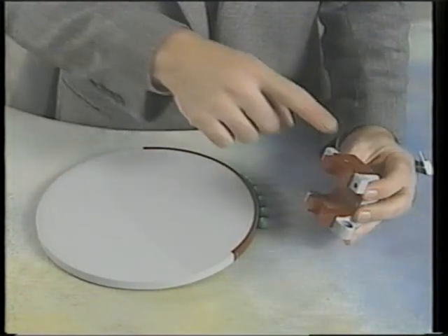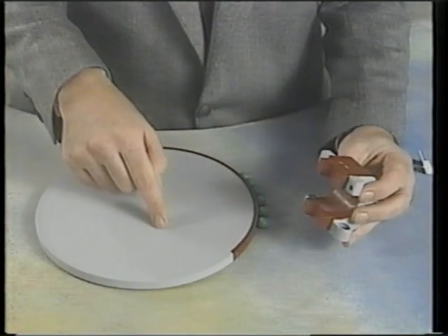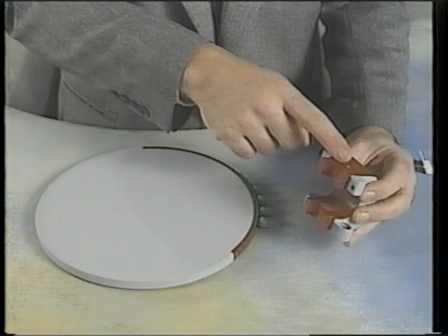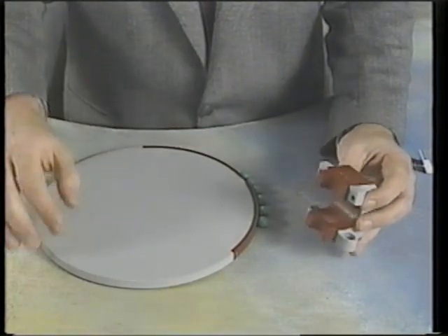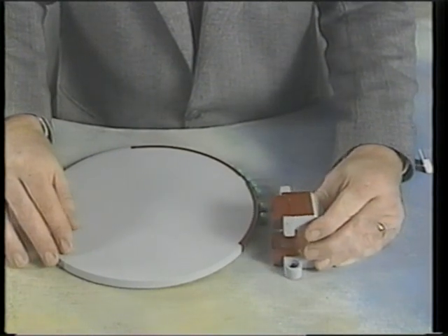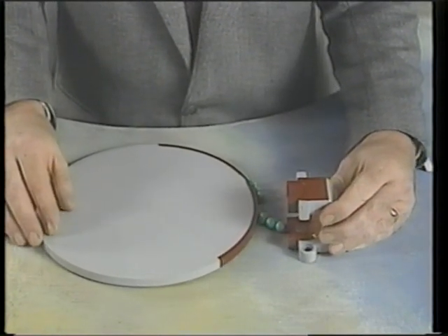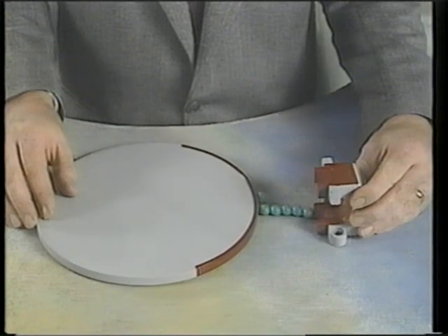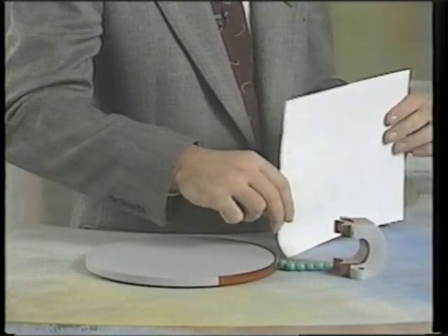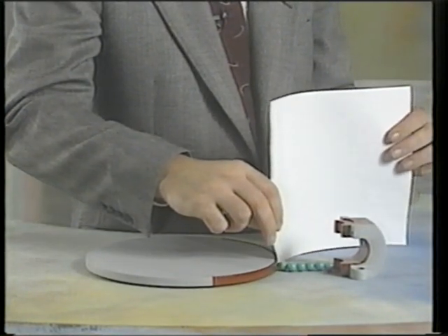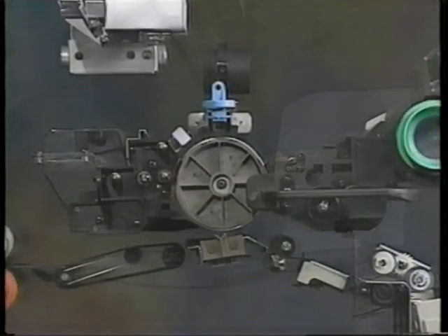It's another case of a strong attraction encountering a weaker one. In a copier, the transfer corona creates an electrical charge stronger than the latent image. The result, when the drum turns past the transfer corona, the toner is attracted away from the photoconductor. There's one other element, paper. The paper feed system is timed so that just as the developed image reaches the transfer area, a sheet of paper is being pushed up against the drum. It happens like this.